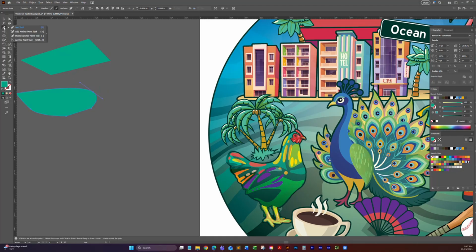And there's a couple of other things too here. Inside of here, if you see a little small triangle, that means that there's other tools in there as well. And these anchor points, you can add an anchor point, delete an anchor point, or you can change the type of anchor point. So adding is exactly like it sounds. If I want another anchor point right there, it just added it, and it automatically put the right handlebars in there for that particular type of point.